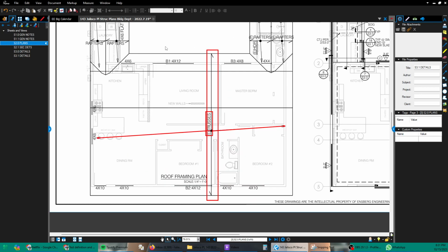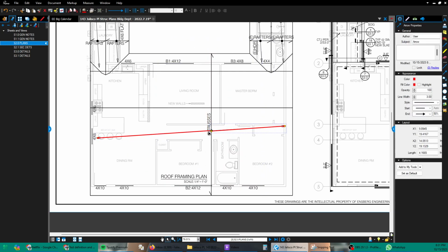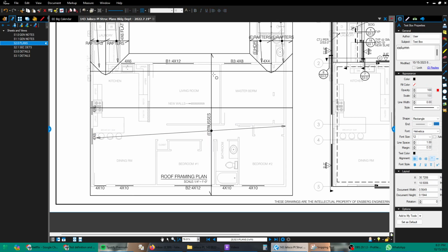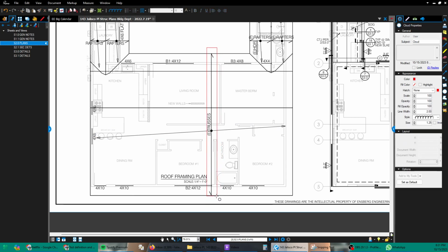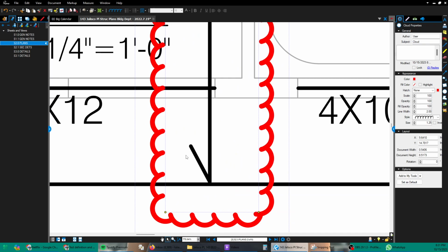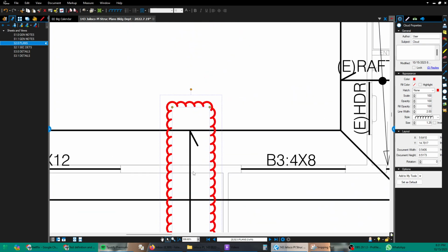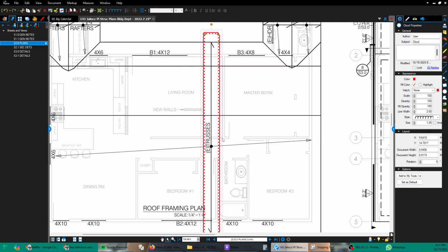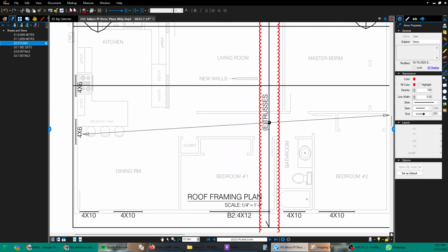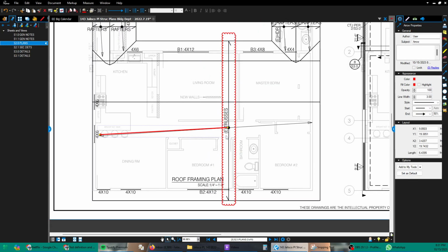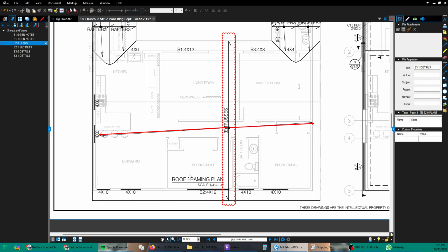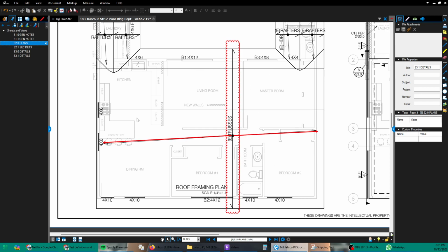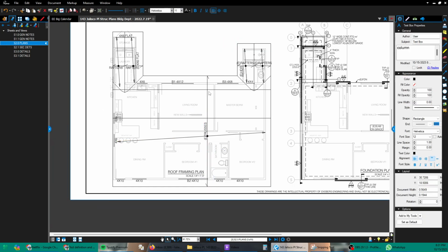So, again, this line in here with the angled edge, the half arrow edge, indicates the extent of a single truss, and these extent arrows indicate where those single trusses exist. They exist along the building. Probably almost always every 2 feet on center does that type of truss exist.